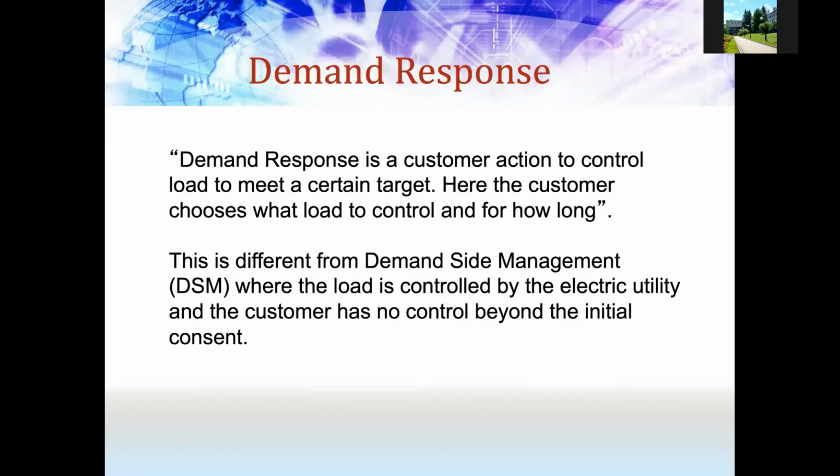For example, on a hot summer afternoon, the power company sends a signal to me that they would like me to drop my peak load by 20%. If it was 20 kilowatts at the time, I can use 16 kilowatts, not 20. So they can save the 4 kilowatts from my house and use it to help somebody else.